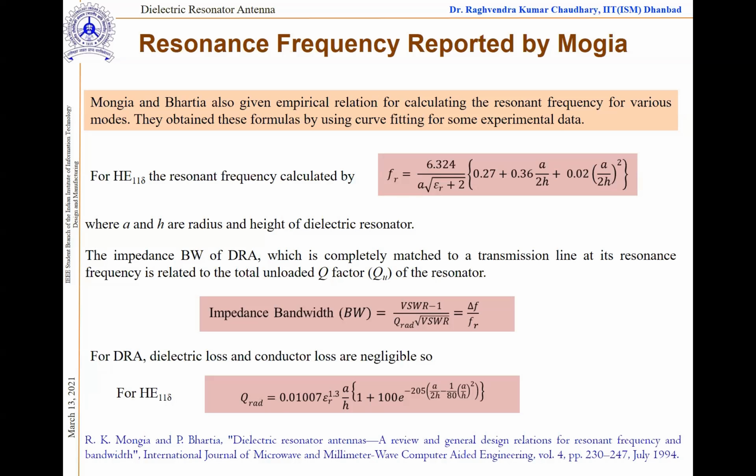But what I suggest is, when you are going for an arbitrary shape, since this is for the cylindrical DRA, you need to think. I do not suggest doing it analytically because it will take a lot of time. What you can do is use HFSS. You can use the driven modal analysis, and if you excite a particular mode successfully, you can predict the resonance frequency as well. I'll show you this.